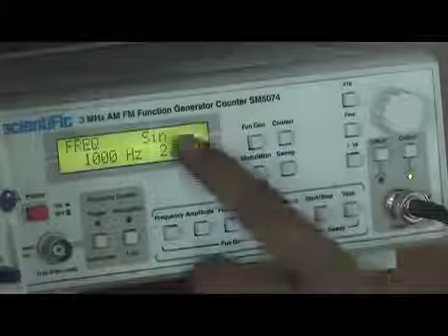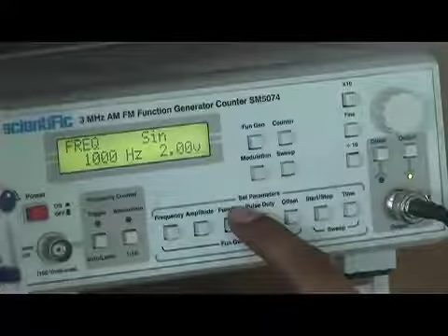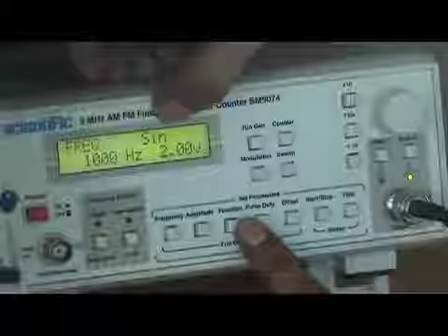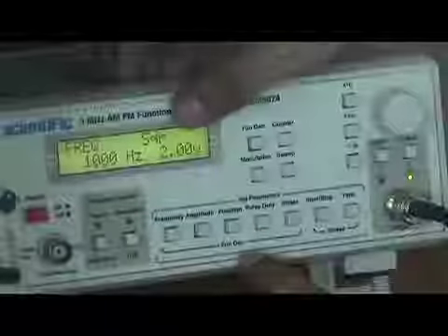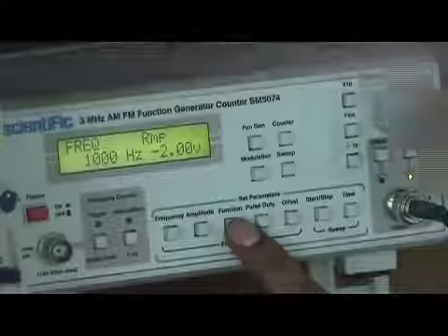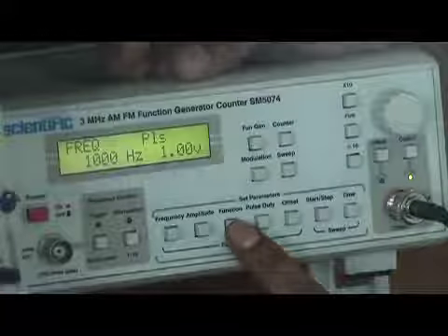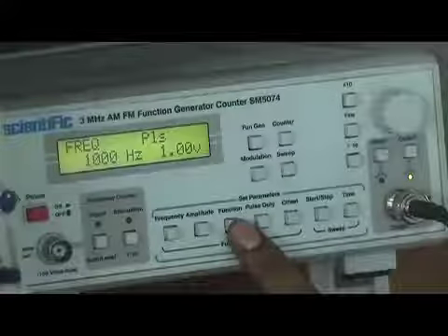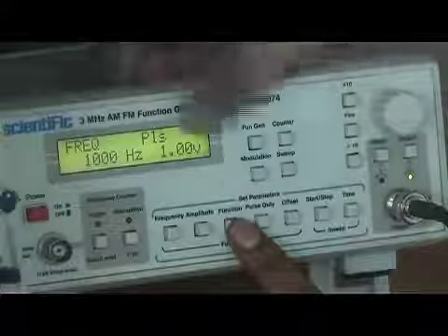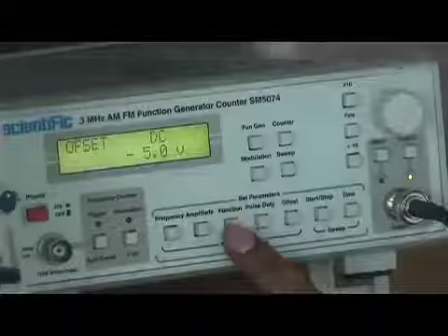Now what is the function? My function is sinusoidal. You can change the function from sinusoidal to various functions like triangular. If you press it again, square. If you press it again, this is again a square. Ramp, it's 2 volt. Again, ramp minus 2 volt means a negative ramp. This is pulse 1 volt, because when we say pulse, it denotes only from reference to the upper level or from reference to the below level. When I press it again, it says a pulse for minus 1 volt, means below. Then a DC voltage, then again back to the sinusoid.